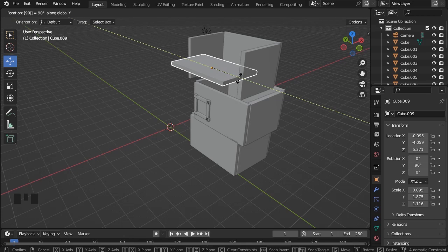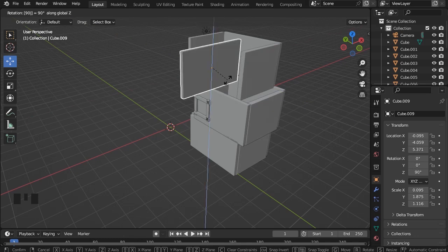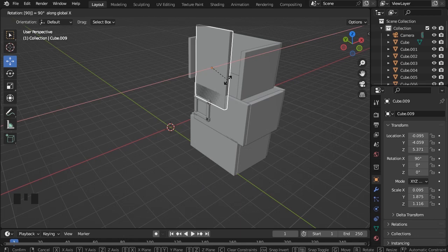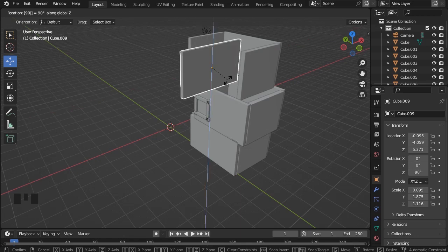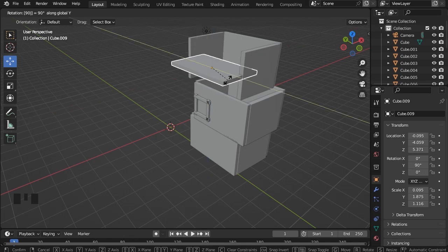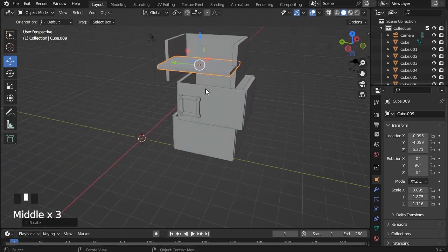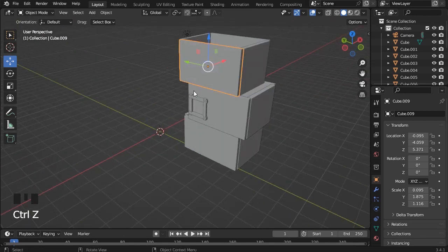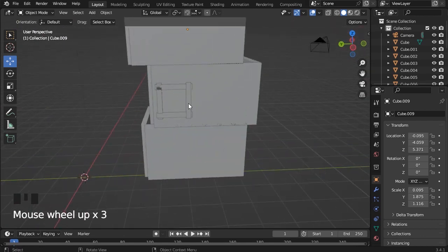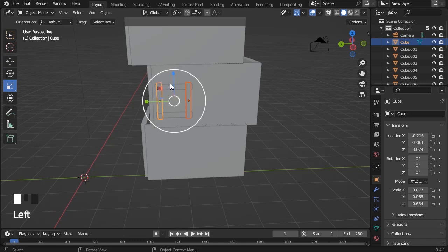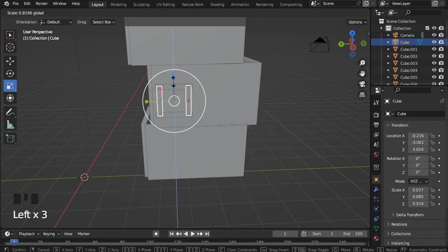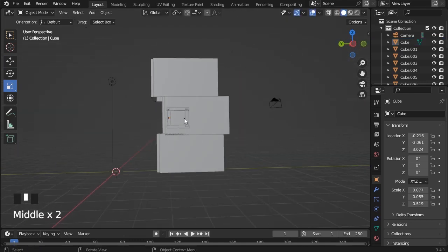So for example, you want to rotate like this shown right now, but you don't know which one it is. So you press X. Okay, this is not the rotation I want. You press Z. Okay, it's not the rotation I want, and you press Y, and okay, this is the rotation I want. You click, and then it'll be that rotation. And then you can press Control Z to get back, Shift click, and shrink this, and then you kind of have a window.